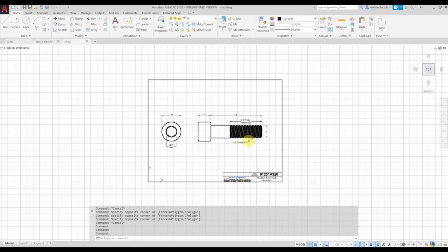The last things I want to show you, actually there are two. One is Ortho, this icon. It's used primarily when you draw horizontal and vertical lines. When you turn it on by pressing F8 on the keyboard or just left clicking on it, let's grab the line command.